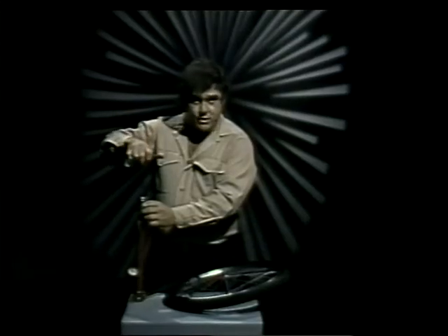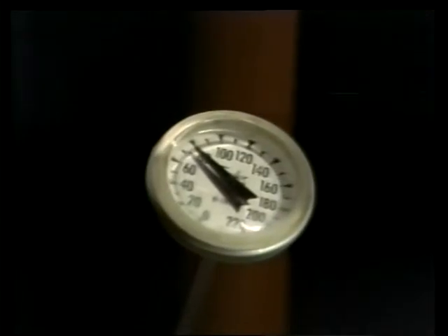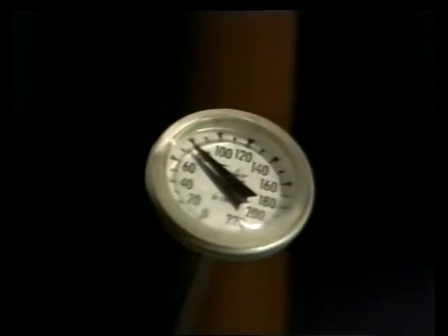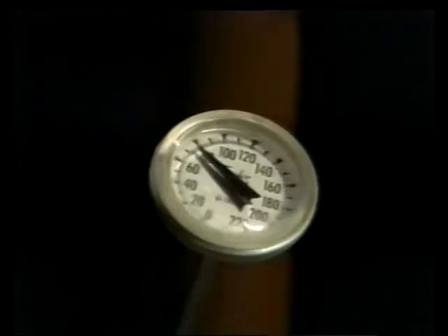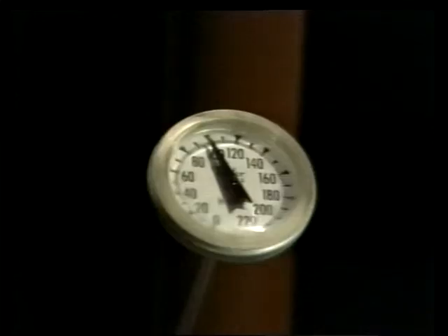To demonstrate this heat inefficiency, I brought along these items: a bicycle pump, tire, and a thermometer. Now, a bicycle pump is basically a small positive displacement compressor. Air is drawn into the cylinder when the handle is pulled up, and it's squeezed together and discharged when the handle is pushed down. Now, this thermometer will show what happens to the temperature of the air while I pump. And as you can see, it's reading about 80 degrees. Now that we've reached the proper pressure for the tire, you can see that the temperature is about 95 degrees.